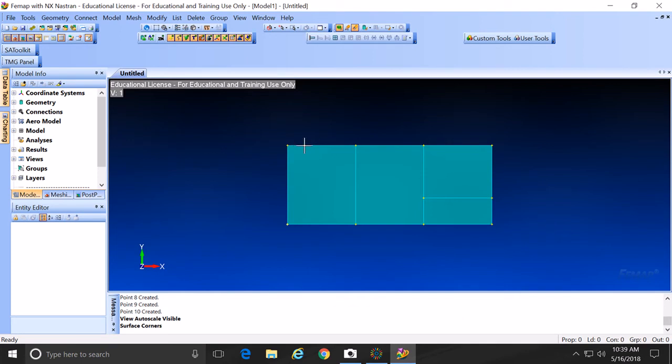Okay, now guys, what I was going to do initially, let's do it, okay? We might have to be careful at the time of meshing, but at least for the modeling will be good. So these surfaces will be modeling the webs or the panels, all right? Now, what do we have around the webs and the panels? We have stiffeners, okay? In order to model the stiffeners, we're going to use some type of element, but let's just do lines now for the stiffeners.